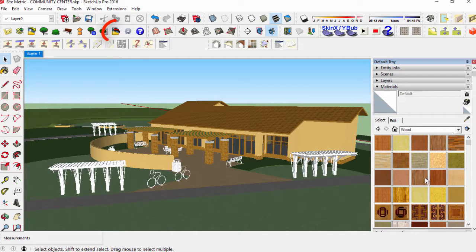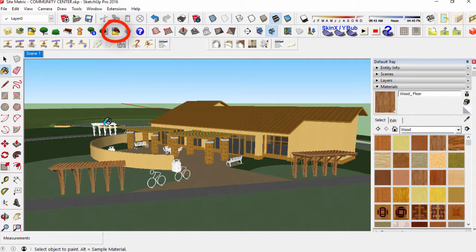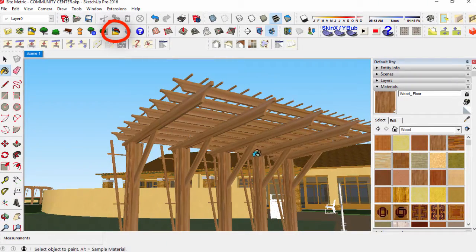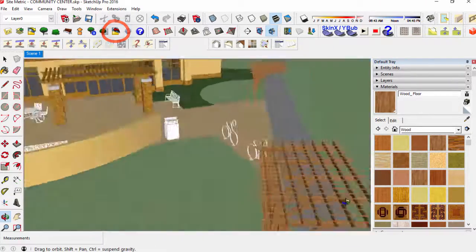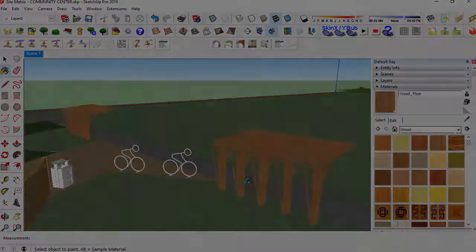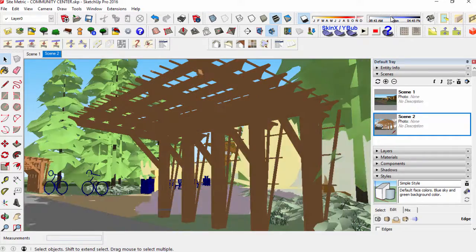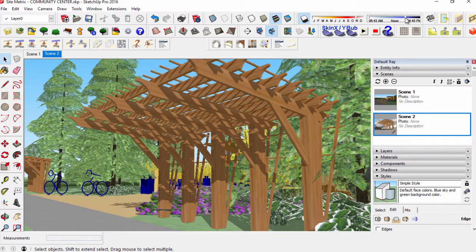If you're on local data, you'll have to re-export this model back to the CAD drawing in order for the SketchUp component information to be saved to the local server data for the reference note. The Refnote will also keep this information if you import it into another project, which is great news if you use templates.